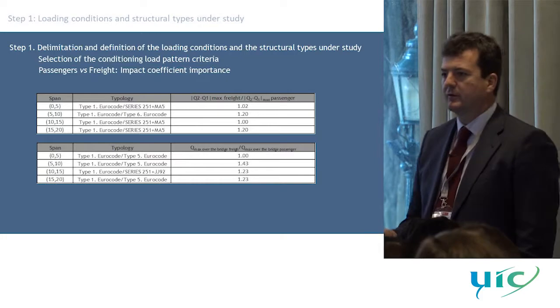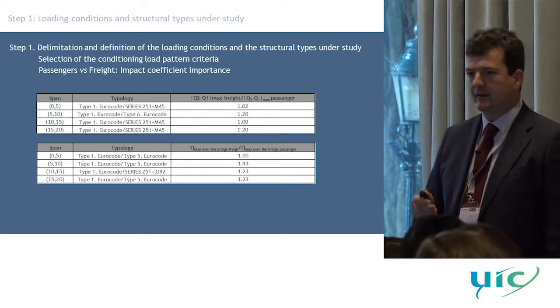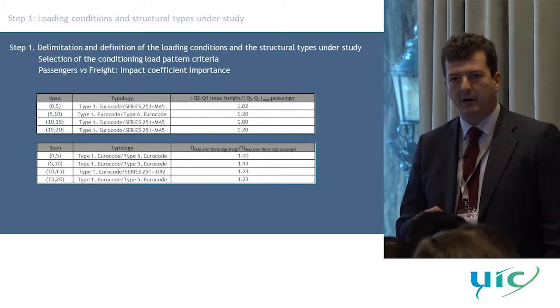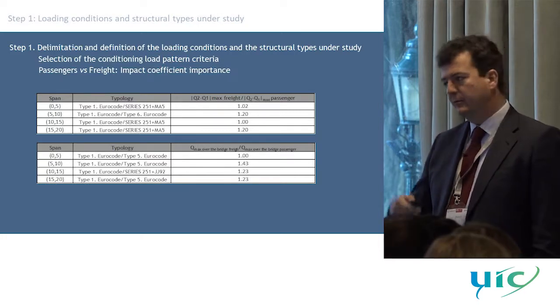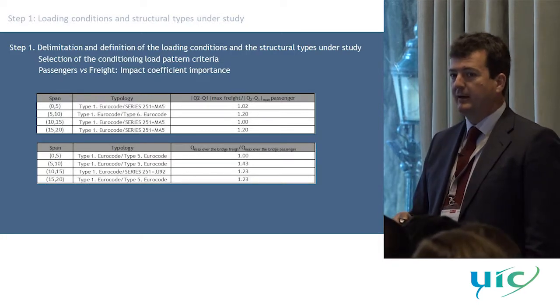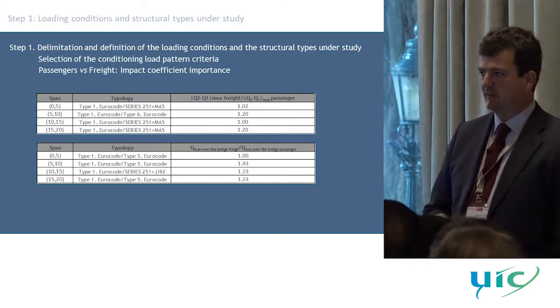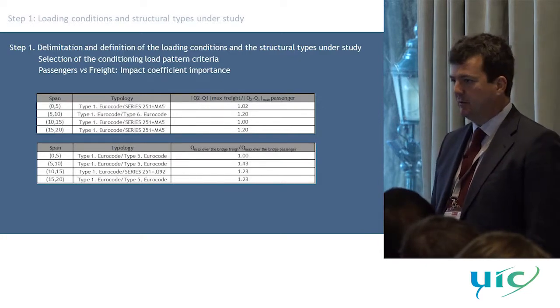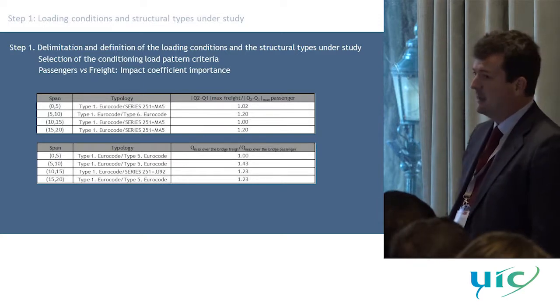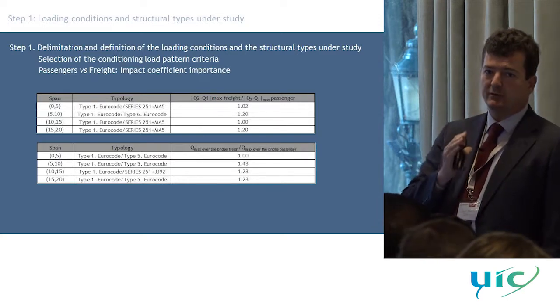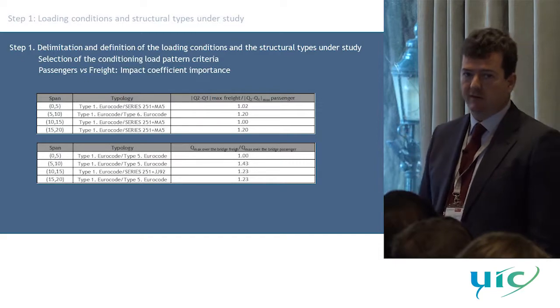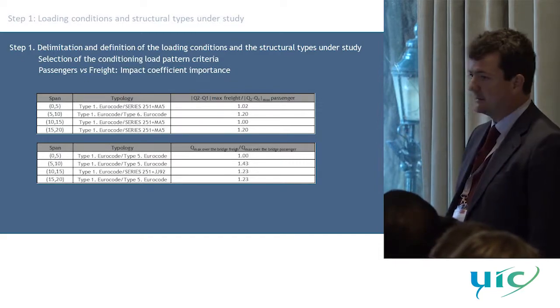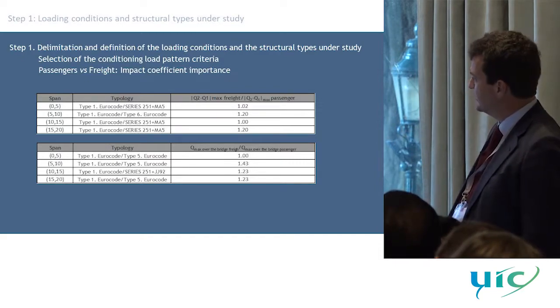So all of this work is gathered and described in one of the background documents. There you will see all the trains that we really have and the difference between the countries. We try to have similar axle loads, but we don't have exactly the same ones. And the other thing that is quite important is that we do not have the same distribution of axles, which is another thing that can matter a lot in these bridges.